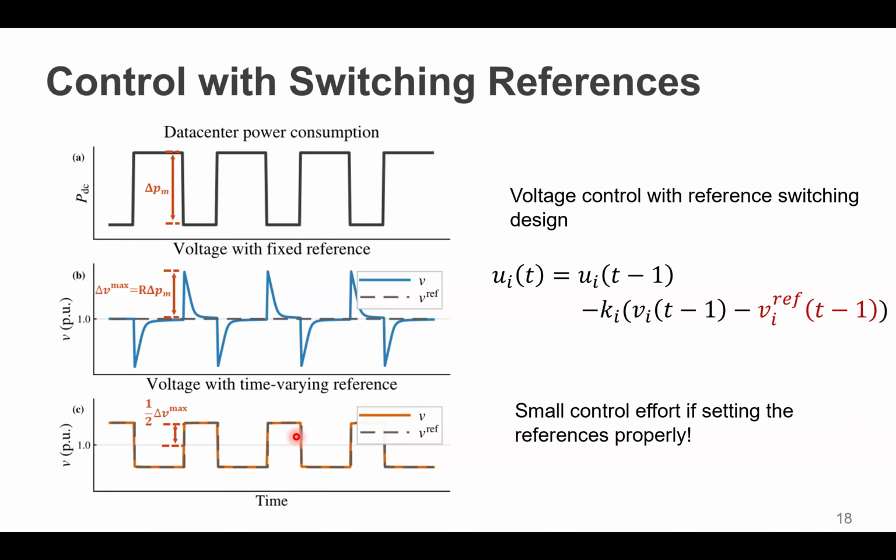It would be nice to clarify how fast disturbances change. Maybe you have some plots, I don't know. It's like if you're sampling something at 1 second, something that is happening at 10 milliseconds, what is actually that you're controlling? I think it's the average over a second, it filters like AGC. Yes, precisely. So it's just going to smooth out over 1 second. We do that in power systems all the time, but you cannot claim that you are then polishing it every millisecond because you're not. The poll is too slow.